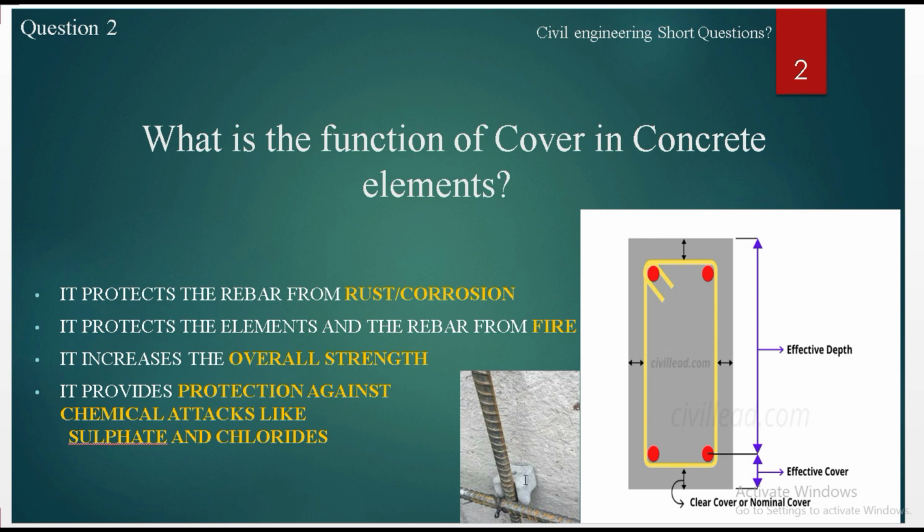They're very common. And the main functions of cover are that it protects the rebar from rust and corrosion. It protects the elements in the rebar from fire, so it acts as fire resistance. It increases the overall strength, and it provides protection against chemical attacks like sulfates and chlorides. So these are the main functions of cover in concrete elements.